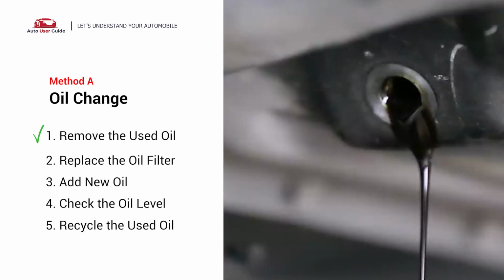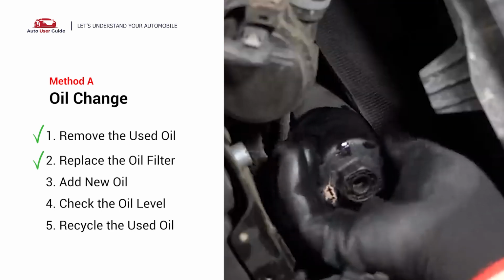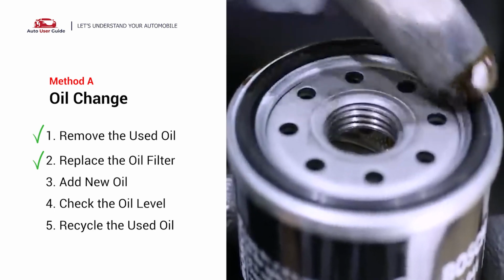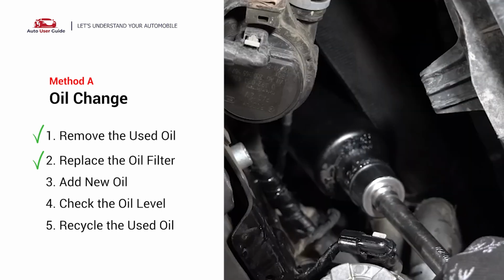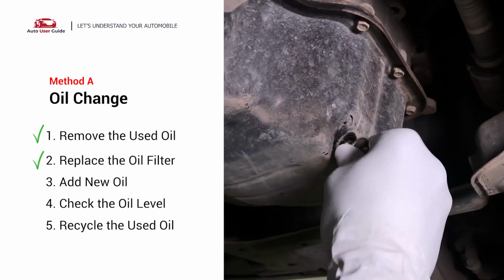When the flow of the oil gets slower, use the oil filter wrench to loosen the oil filter. Apply some seal on the new oil filter. Now tighten the filter in its place. Then retighten the nut.